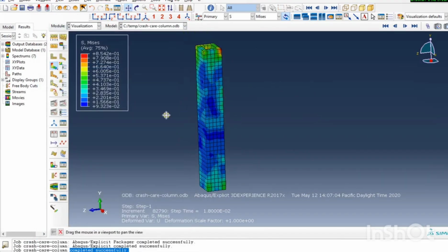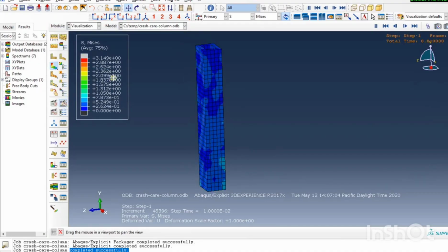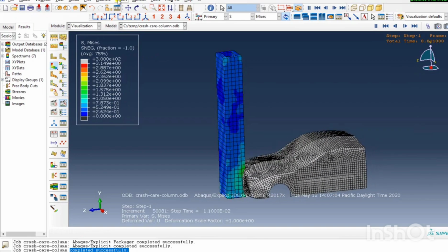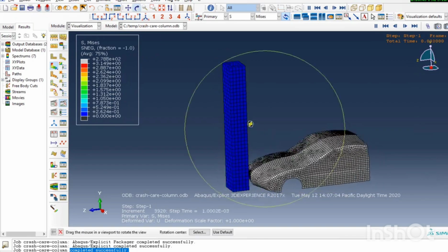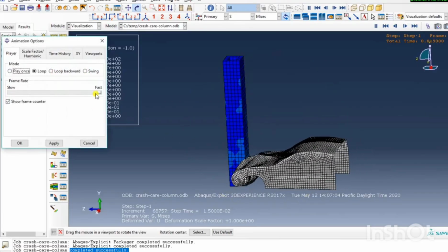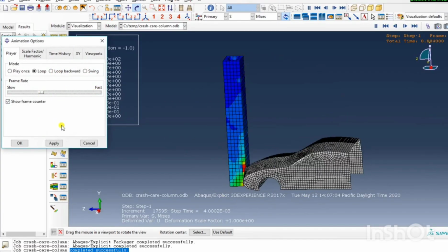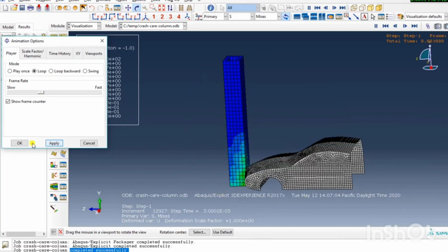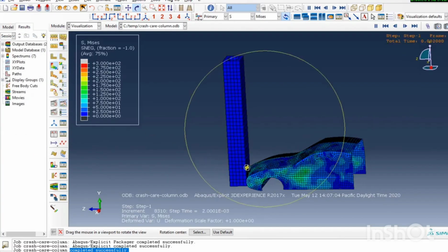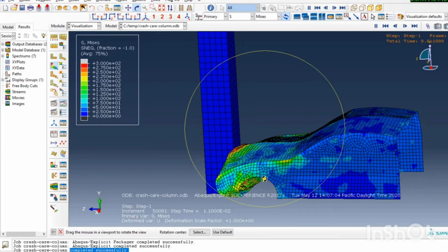If we are using the implicit solver for the impact analysis, then at the onset of impact, the stress wave propagates through the structure, requiring very fine time resolution. As deformation progresses, plasticity develops. These high frequencies are then damped, which allows slightly larger increments without loss of accuracy. So it depends upon us as analysts which approach we use for the crash simulation.